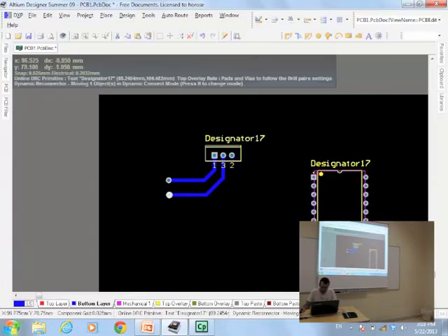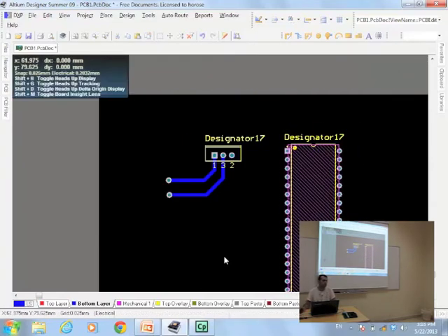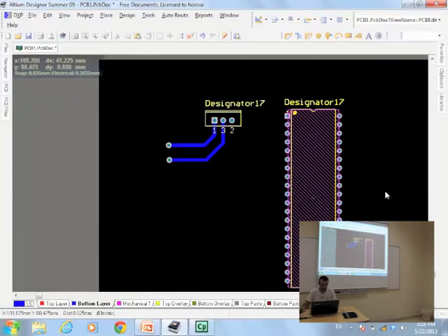Let me just bring it very close together. One of the things on these kinds of designs, try to compress everything as much as possible. Although sometimes you need to make it bigger for other kinds of stuff, with microcontrollers like this, compress them together. Pin number 11 is VDD.